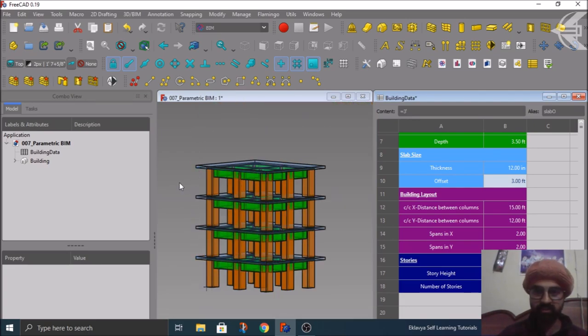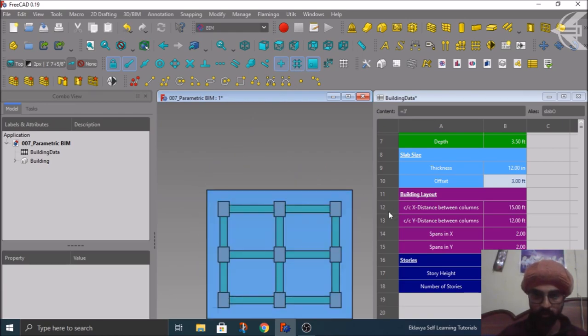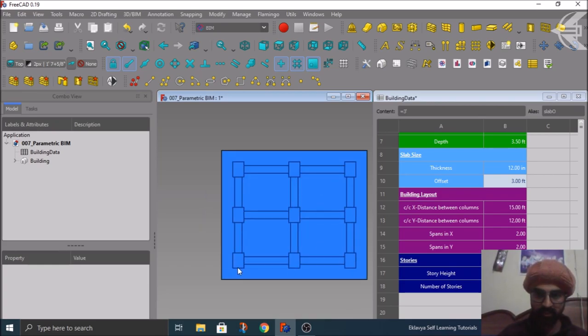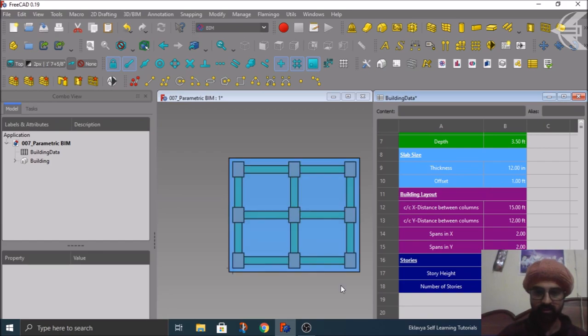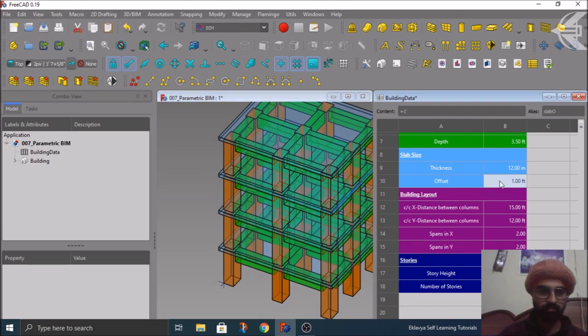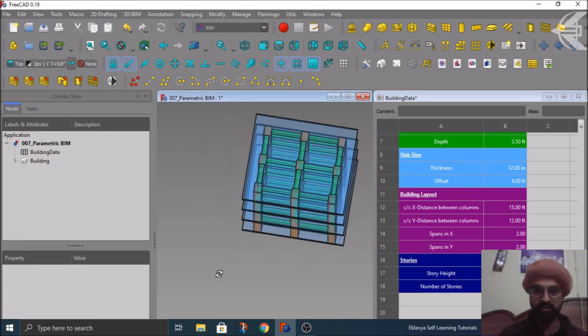Now the offset, basically, if you just see your top plan, these outer boundaries with your main structure within. So this is marked as 3 feet from all sides. Let's make it 1 foot, and you can see it has shrunk. So it's quite less. We can move with 4 feet, say, and you can see the offset has been synced with your model.